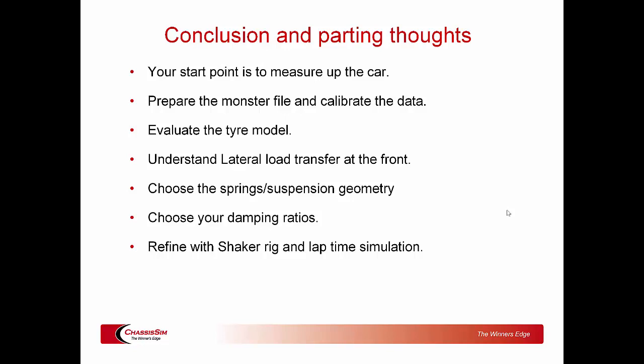I cannot stress enough, you always measure up the car and you prepare the monster file and calibrate the data. Let's put it this way, in the chassis sim boot camps, those 2 points I spend at least an hour and a half on, and that is no accident because of the old saying, garbage in, garbage out.